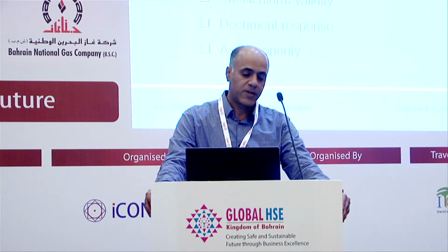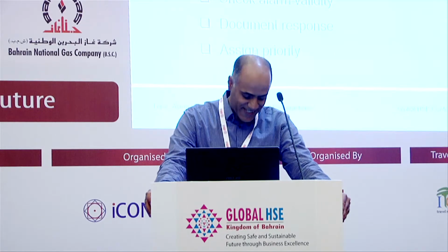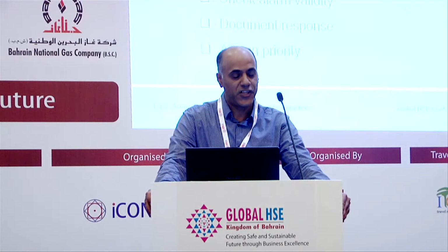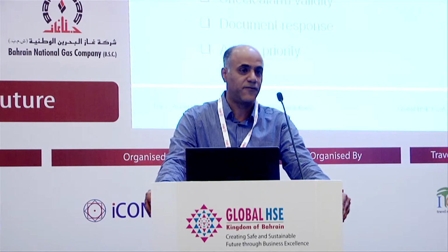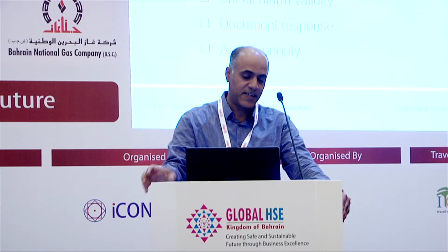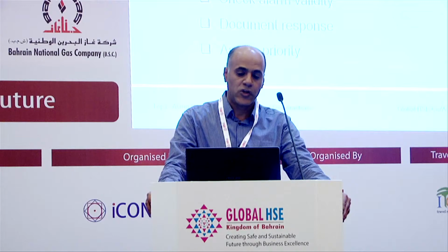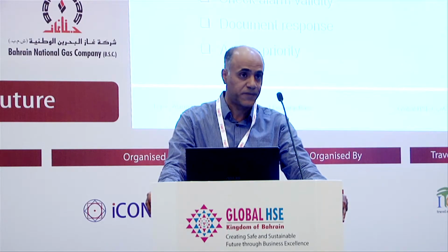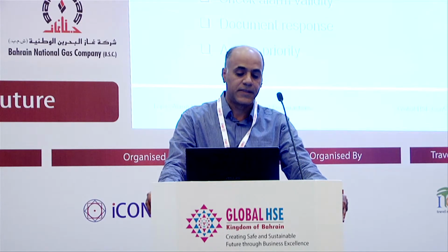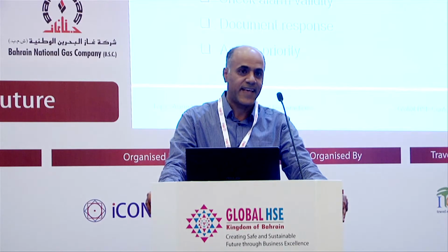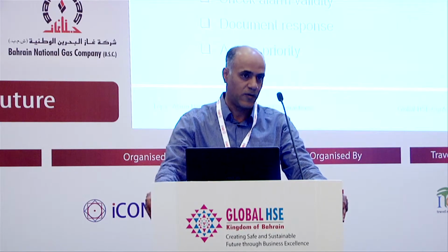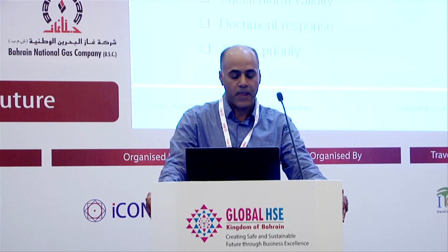Then we'll go to the rationalization part of the process, which is examining each tag and making sure that it really fits and meets the criteria of the alarm definition. So we may ask questions like, does this tag meet an alarm criteria, and does it require an action from the operator? And what is that action that is required for the operator to do to prevent the escalation of the process into an ESD system?